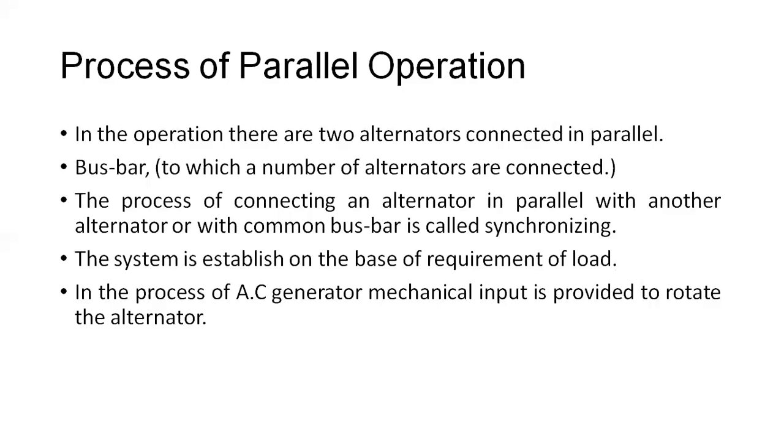Here, synchronize means the two or more alternators, their resistance as well as the synchronous reactance, and most importantly the terminal voltages, phase sequence, all the criteria are matching with each other. When all conditions are matched with everything, that process is called the synchronizing process.